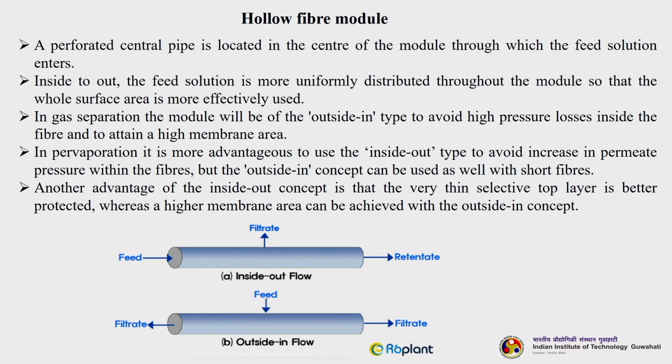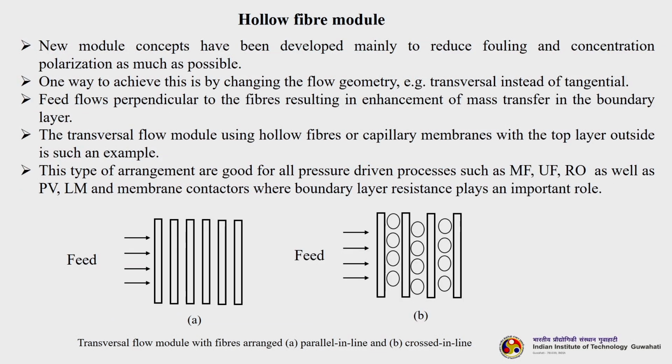So, if you go for an inside out concept and you have composite membranes where the surface layer is very thin, it should be protected, otherwise there will be wear and tear. Then inside out is better, and if you want to achieve a higher area, then outside in is better. So, there is no such thumb rule that you are going to recommend. It all depends upon many factors. We have already discussed the factors.